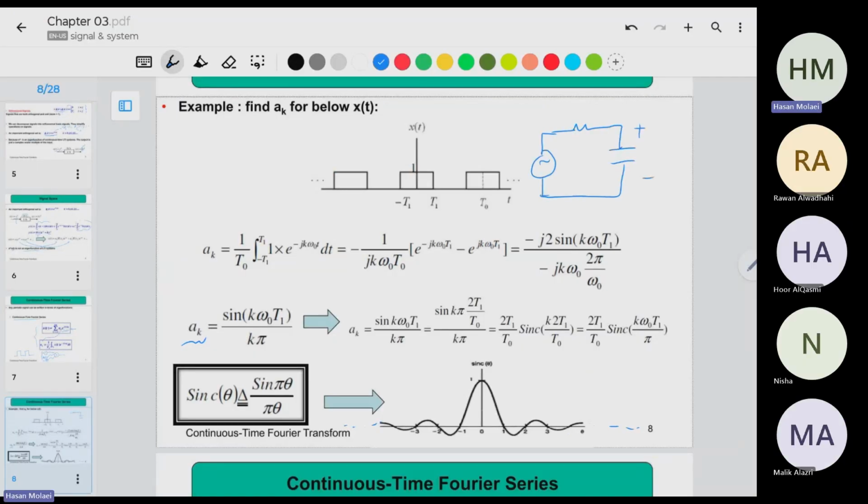If I consider here as the output signal, if I see this output signal in a frequency domain, omega, if I change the frequency of the source, how would be the impedance of capacitor? It's gonna be decreasing, yeah? It's 1 over JC omega, that's its impedance.